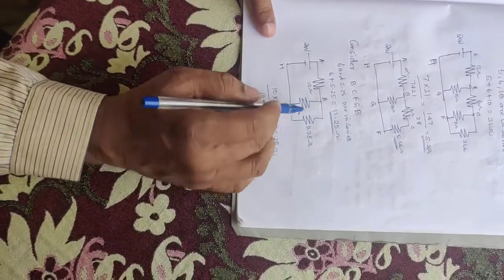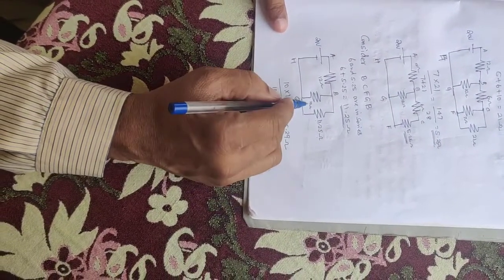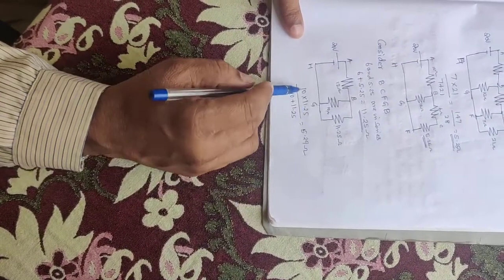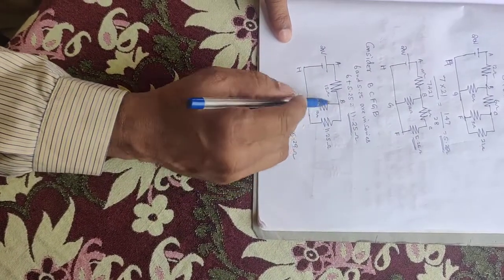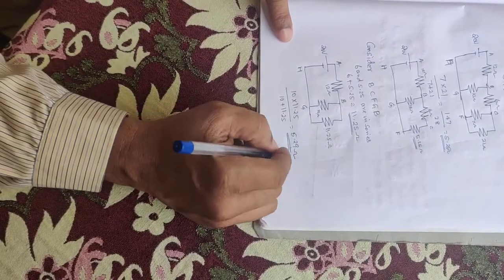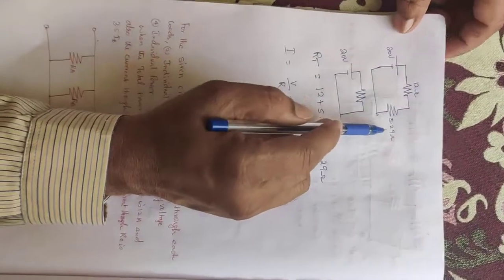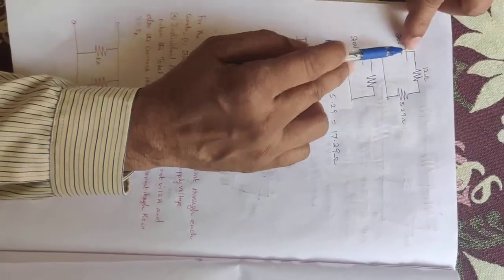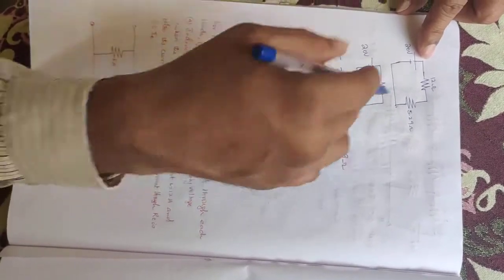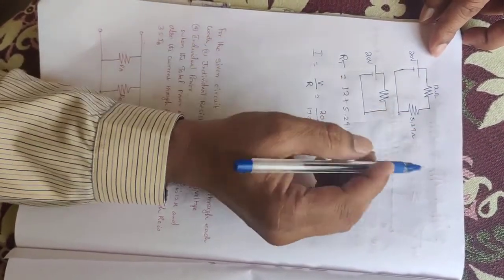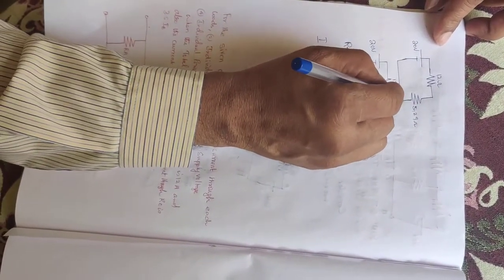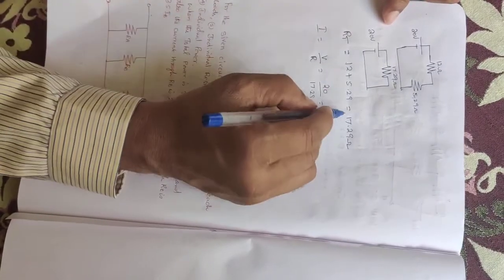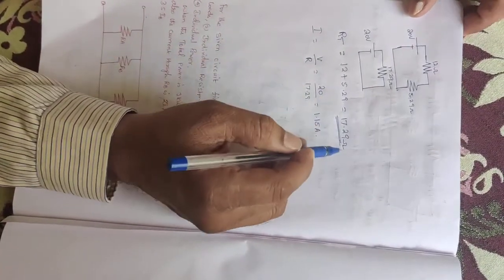Now rearranging the circuit, 11.25 ohm is in parallel with 10 ohm. Using the formula I am reducing to 5.29 ohms. So these two are converted to a single resistance of 5.29 ohms. Rearranging the circuit, I am getting 5.29 ohms and 12 ohms across the 20 volt battery. Now these two are in series. So by adding these two, it will be reduced to 17.29 ohms. So the total resistance will be 17.29 ohms for the given circuit.